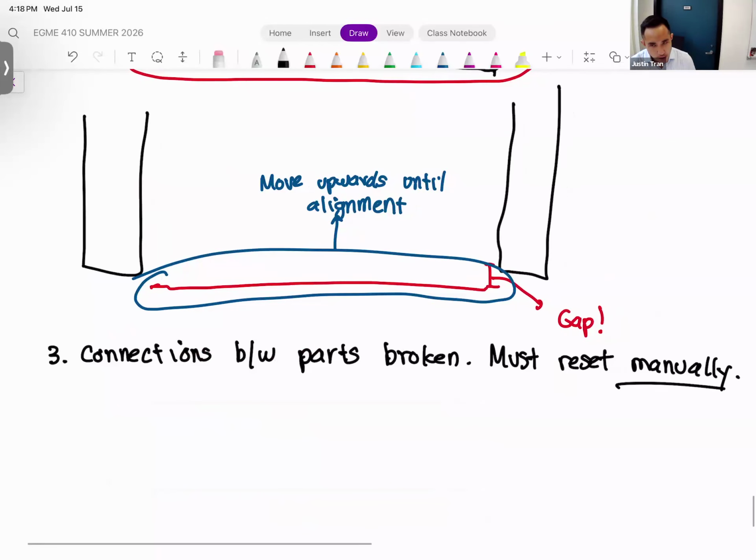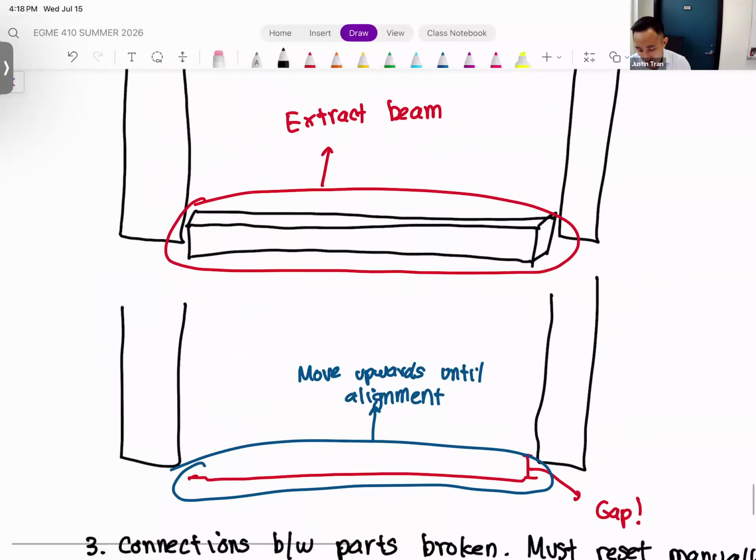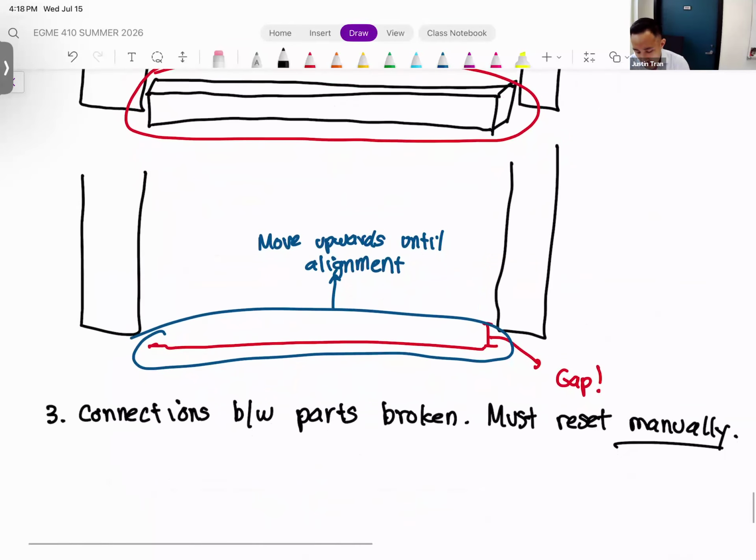So again, activity four, not my favorite. It is very tedious. There's kind of a lot of fixing we have to do. But if your geometry is well suited for shells and beams, it really does save you a lot of computational resources. And a lot of times it's necessary. Otherwise, you would need millions and millions of elements to mesh your geometry.